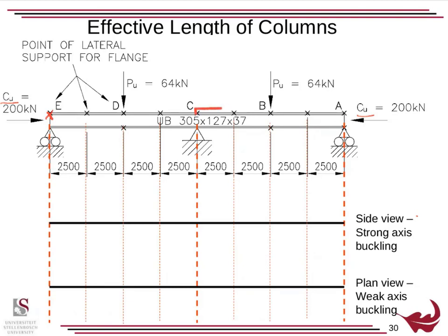Well, think about it this way. Imagine if there was a floor on top of this section, a steel grating or a steel plate, and the floor sitting on top. And this floor is connected to other beams, and it forms a sort of rigid system on top of it. It prevents sideways movement, especially if we fix the floor there, there, and there to the beam. When we load this steel grating, it will move up and down with the beam.